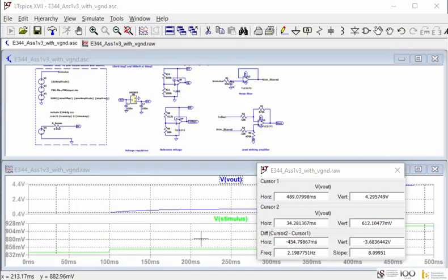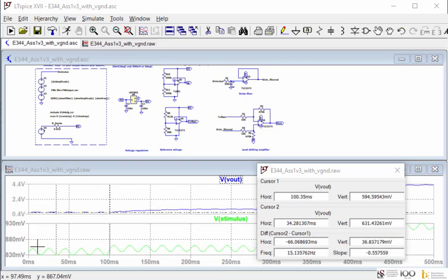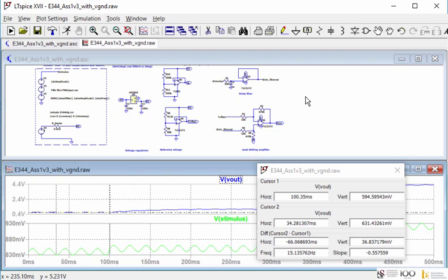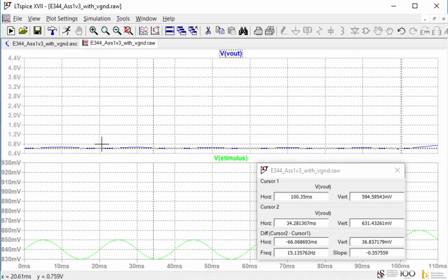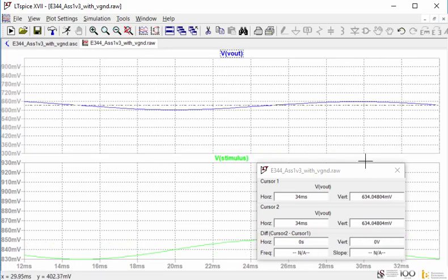Right, so if I add back the noise, then you should see that the noise is still within the limits of the specifications. So as you can see now, I still have this noise on the input. I'm just going to blow this up slightly. There's this big 1 degree amplitude sinusoid on top of my signal. And if I zoom now, despite the fact that I'm meeting the rise time requirement, you should see that I'm still meeting the objective of limiting the noise or suppressing the noise. Just get my cursors back here.